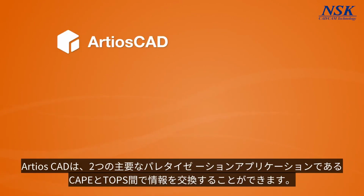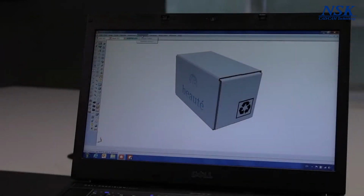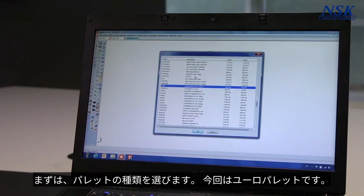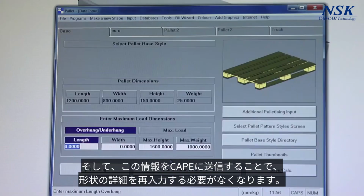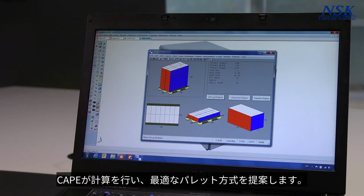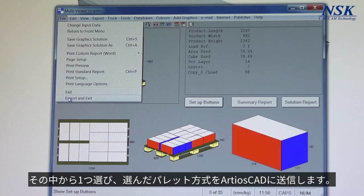ArtiosCAD is able to exchange information with the two major palletization applications, Cape and Tops. Let's use Cape here. We first select the pallet type, in this case a Euro pallet. We then set some parameters per pallet. Finally, we send this information to Cape without the need to re-enter all the geometry details. Cape will make the calculations and suggest the optimal pallet schemes. We select one and return this pallet scheme to ArtiosCAD.